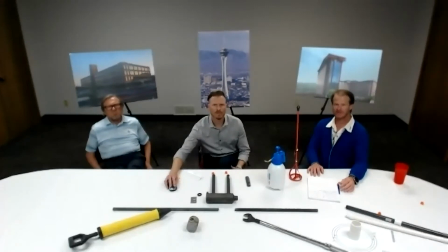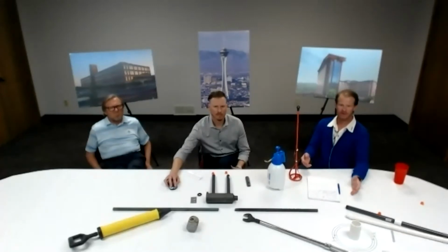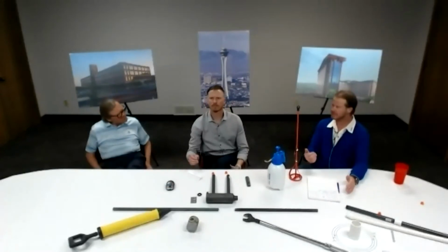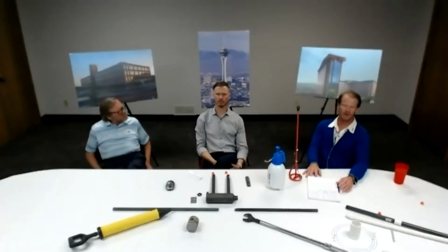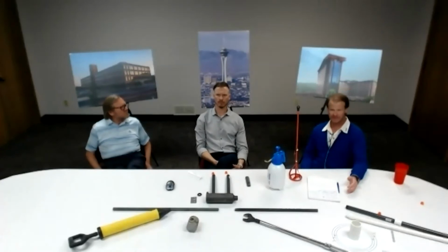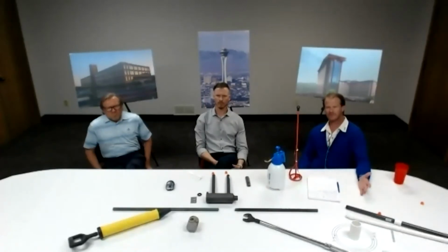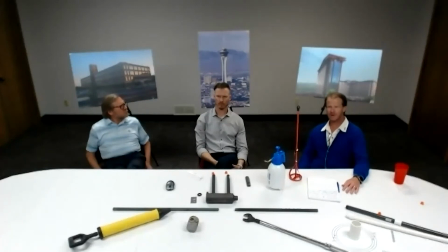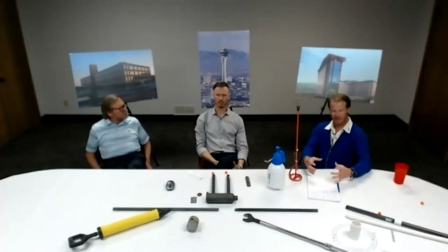Another way to look at it is, yes, we can have them grouted, epoxy. Adam Simet with Simcoat right down the road, they make epoxy coated rebar. They have the facilities to do it, and he's already agreed to do it. The other side to look at it is, we've been involved in post-tension repairs, and what we always do is in the field we just paint them with a similar type coating.